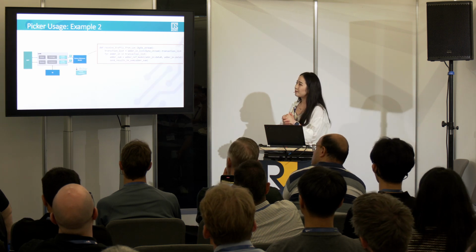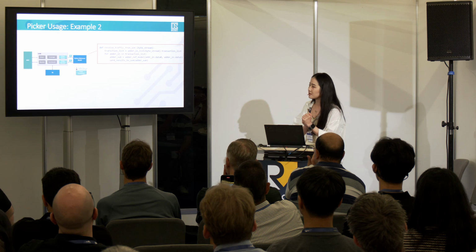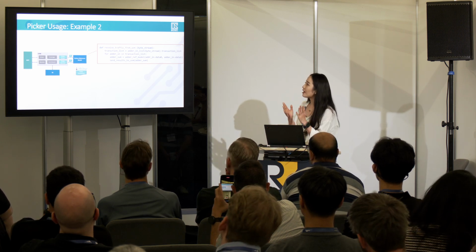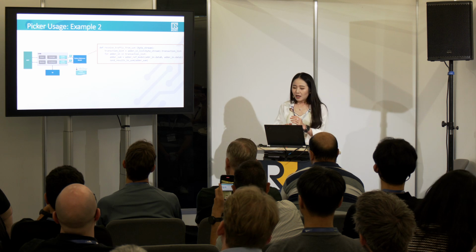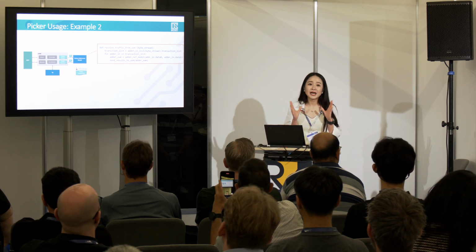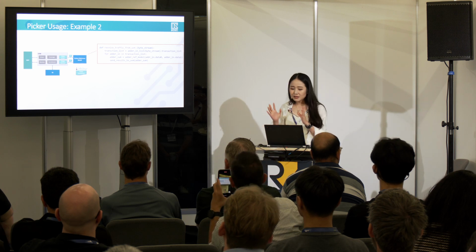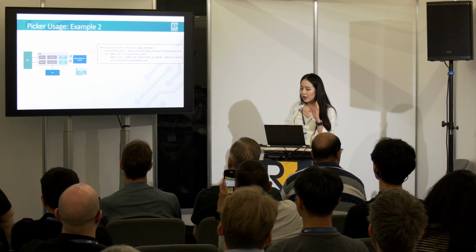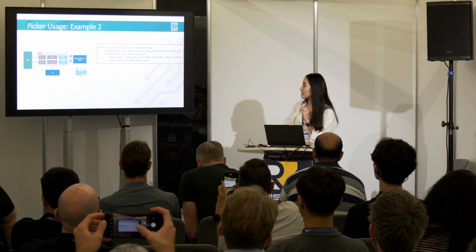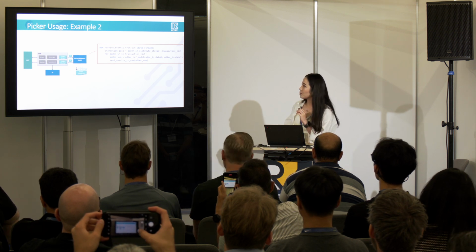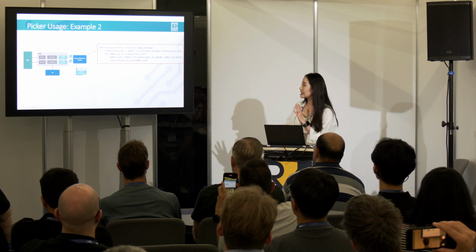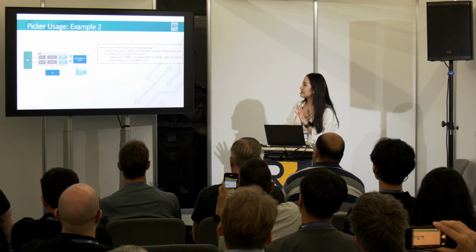Next, in your Python code, there are mainly 2 functions you need to define. The first function is receive traffic from UVM. The traffic sent from UVM is actually a byte stream. What happens in Python? The picker converts the byte stream under the hood into a transaction list. So you can simply iterate through the transaction list to get the data 0, data 1, and send it into